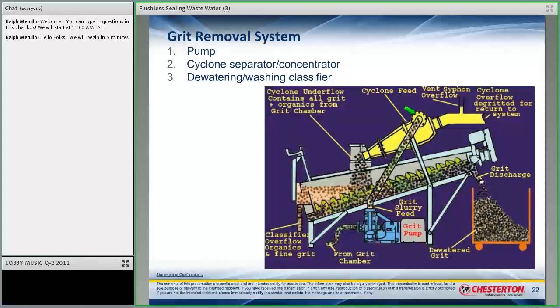We get high speed here, high speed separation. The solids go down in here. So it's all about separating the grit from the fluid. Okay. So the purpose of the pump is to increase the velocity of the fluid as it feeds the cyclone to separate the solids from the fluid. And then there's an overflow up here, and the fluid is removed at some other point in the cyclone. So this whole clarifier here is to remove these solids.